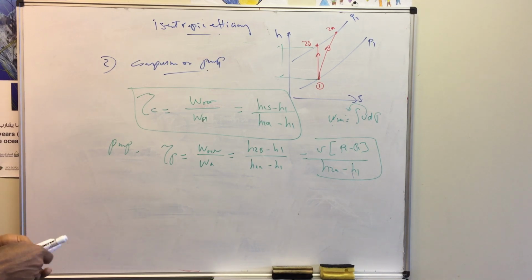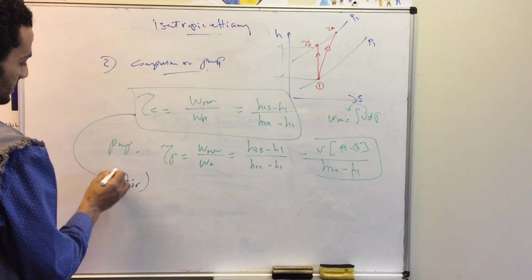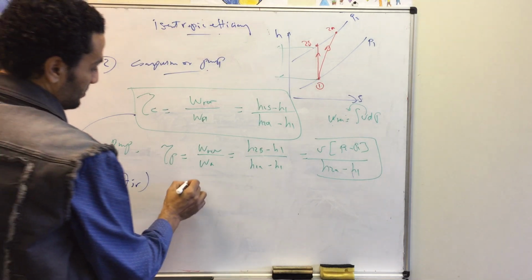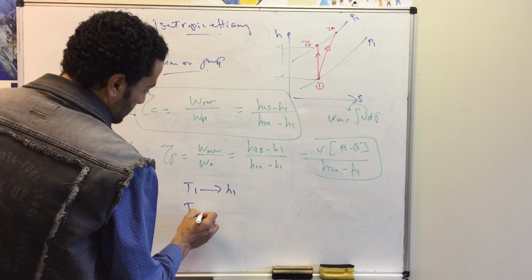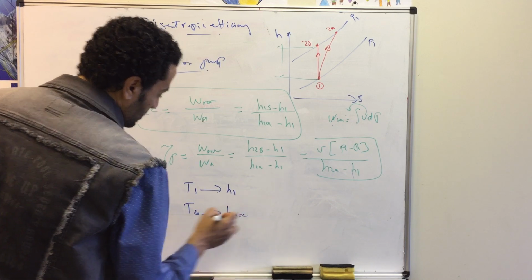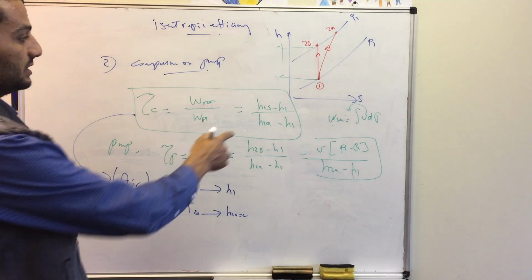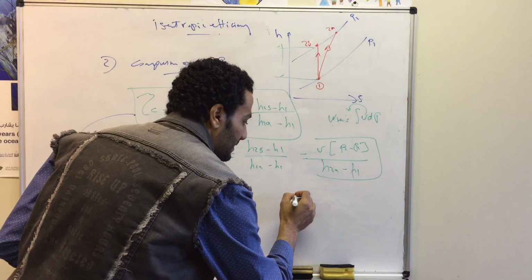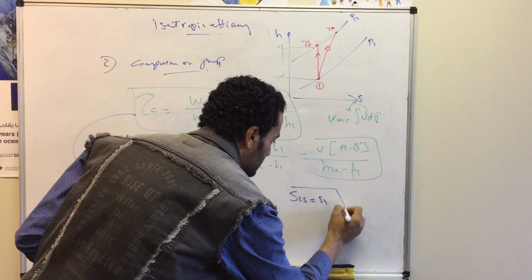But a compressor is usually dealing with gases. Mainly compressors are dealing with air. So if you do have air at temperature T1, we can get h1. And at temperature T2 actual, we can get h2 actual. Okay. But what is the relation by which we can get point h2s? The relation between point 2s and point 1 is that s2s is the same as s1.